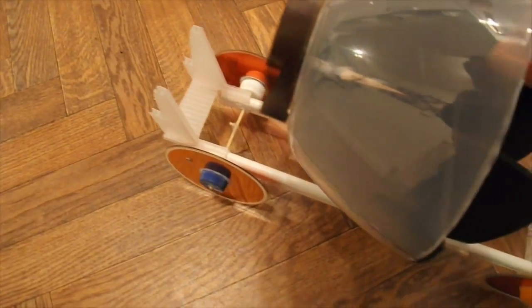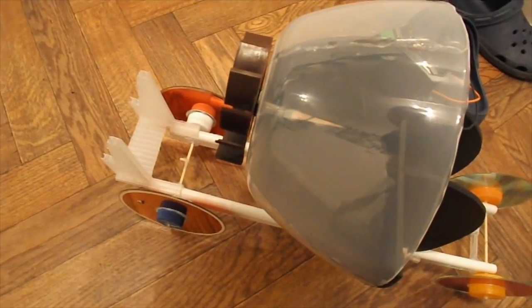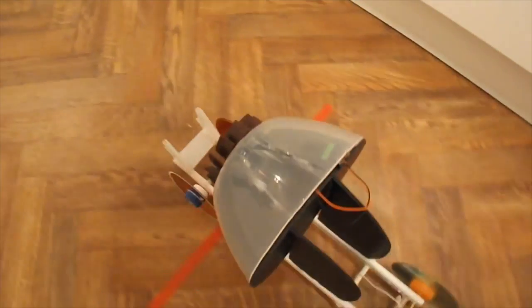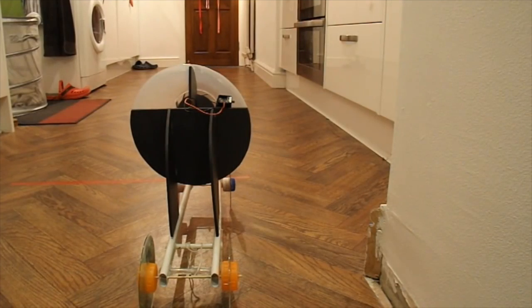That seems to work. Oh, I can smell the motor overheating, because that's really only a 1.5 volt motor and I'm running it on 9 volts. I'll let it cool down and then we'll give it another run. The main problem with it overheating is it melts the hot glue that I've got it holding in place with. Well, that and the fact that it burns out. I'll give it one more go, but I think I may have cooked that motor.